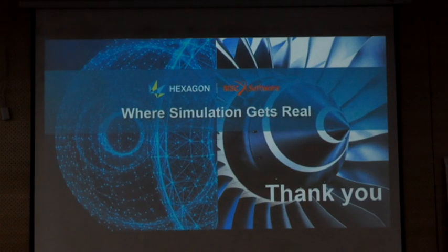Sir, finally, which one is better, subtractive or additive? When complexity is high, additive manufacturing. When complexity is simple, subtractive. So with additive manufacturing, we say that it is not going to replace anything. It will be complementing, because complex design with conventional methods is difficult, so there additive plays a major role. It will be one of the substitutes. It is not going to replace casting and machining, no, because many 3D printed parts are machined for a better surface finish.